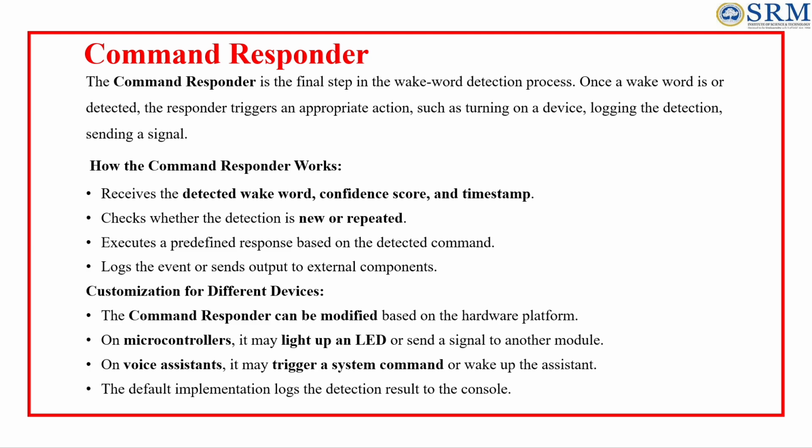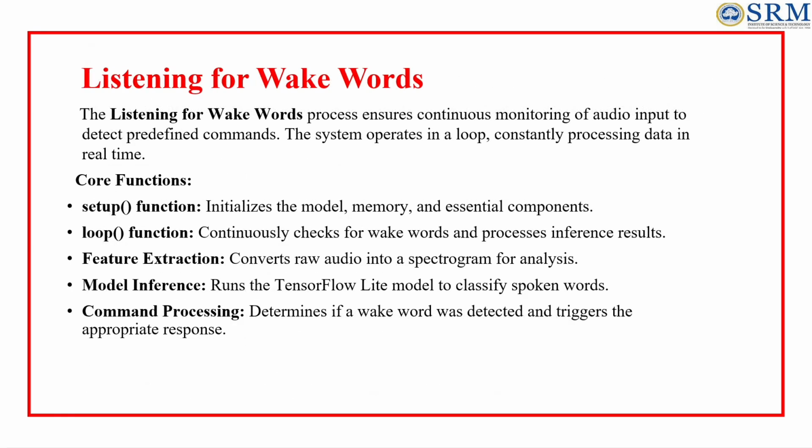Okay, next we will see listening for wake words. The key idea here is that the microcontroller is always running in a loop, continuously monitoring audio from the microphones in real time. There are a few core functions at work here. First one, the setup function. This runs only one time. It initializes everything we need: the TensorFlow Lite model, memory buffers, and any hardware components like the microphone or LED. Think of this as the system booting up and getting ready to listen.